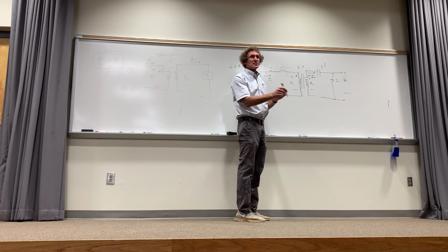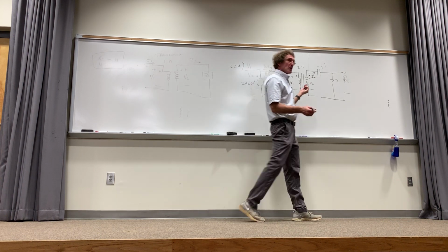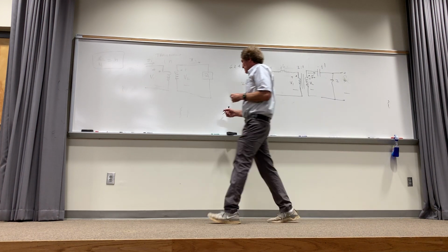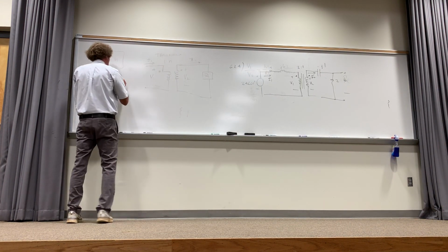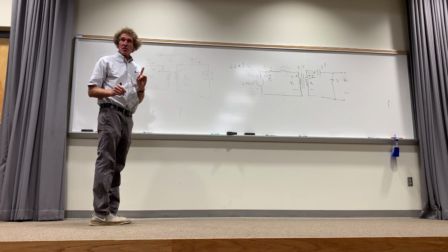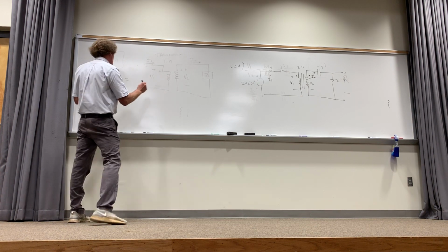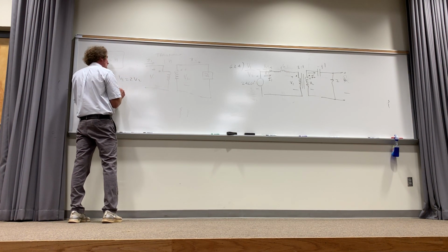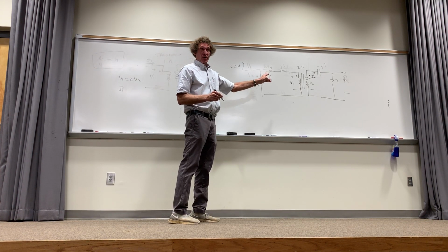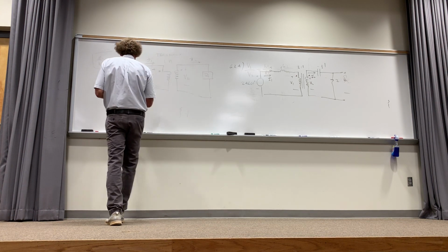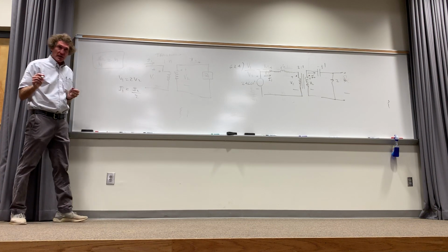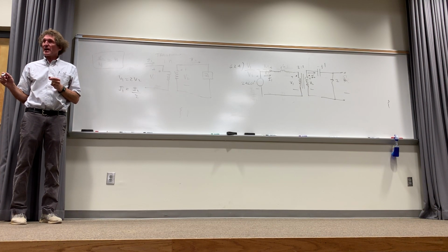Isabel? You remember how I said that when you reflect things, normally if I looked at V1 here, this way, work with me and you'll see it. V1 is equal to what? Well, V1 would be equal to 2 times V2. Do y'all see that, class? So it's 2 times V2. Now what about I1? Well, I1, more turns, less current. I1 is going to be equal to I2 over 2. Got it? Can y'all see this? Everybody got that?